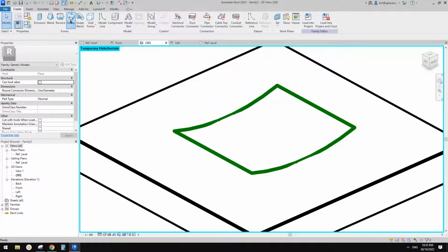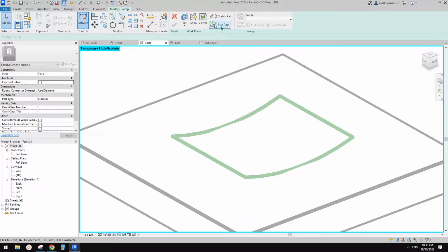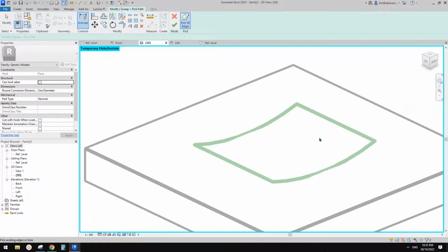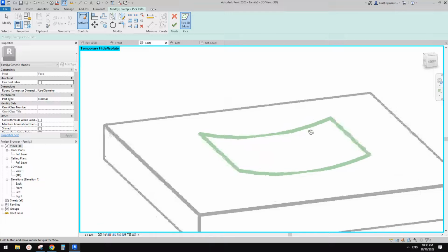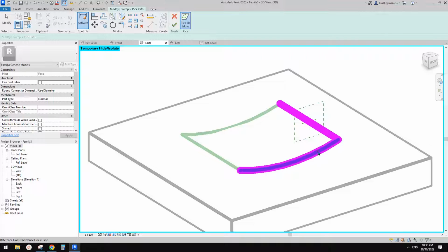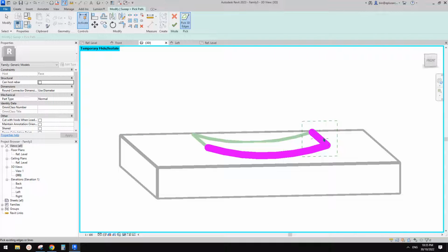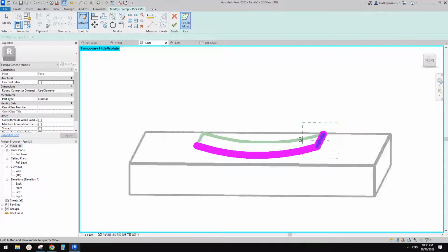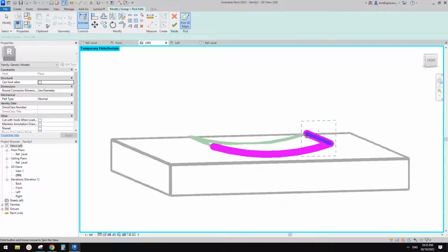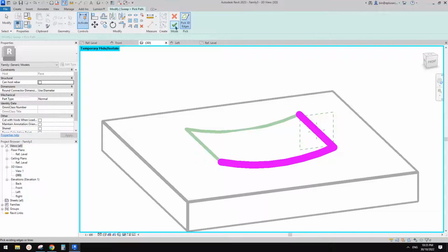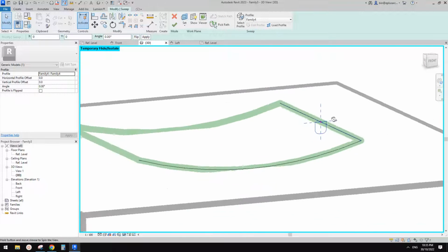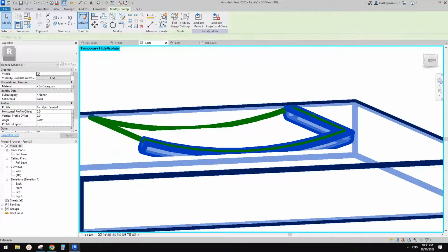sweep. So create sweep. I'm going to use pick parts because we already have all these reference lines, and the one that you first pick is very important because this one will decide the orientation of the profile. So if you pick this one first, you will see this profile, the direction of the work plane or reference plane, it's actually not what we want. So imagine if you place, so I'll just finish this one and then pick this family 4. So you can see it's not right.